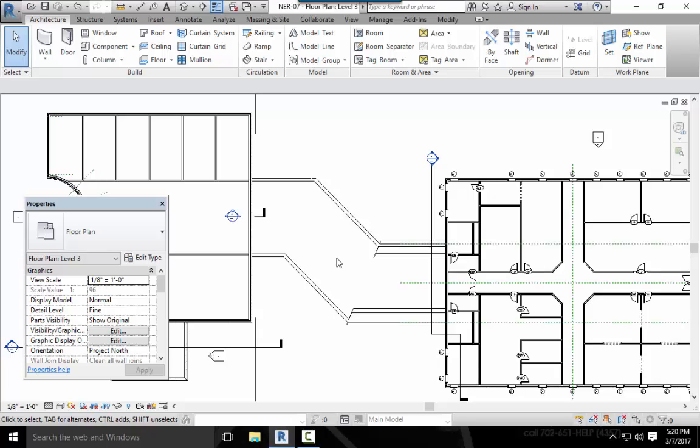Item 7, start the roof by footprint command again on the architecture tab. You can also select the roof and create similar on the modify roofs tab that is currently active. On your own, sketch the roof as shown. Make sure that the lines along the wall are defining a slope. The lines that represent the ends of the roof don't slope.